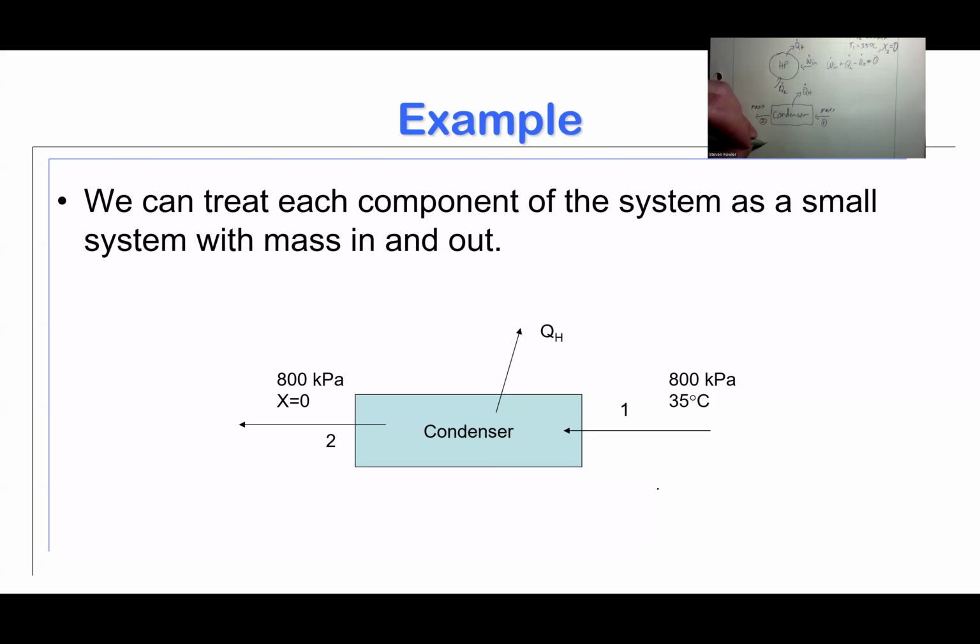So I've got minus Q dot H, according to the first law for this control volume. This is now a chapter 5 problem. This guy is Q dot H, and rather than say equal to, let's put plus the mass coming in. That's M dot times H1, and the mass going out minus H2. I'm not going to worry about the kinetic energy. We talked about how we know when to worry about the kinetic energies. It's not asking for the kinetic energies. It's not given. I don't know the areas, so we're going to assume that the kinetic energies are negligible compared to the enthalpies.